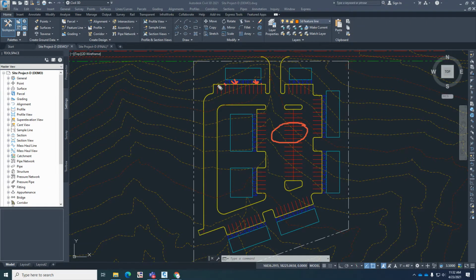From here this way, it depends on what you want to do. It is going to be part of your design, but at least we have the 2% of the sidewalk. So it's going to be basically flat along the sidewalk, along the front of the building. And that's really going to be in all cases in front of the building. So water won't be running this way per se. It's actually going to be running away from the building in all cases. Just like here, it's going to be running away from the building. Here, we basically do need to be flat, the same elevation from here to here. So somehow we need to get the water to drain this way, and same thing with this building here.